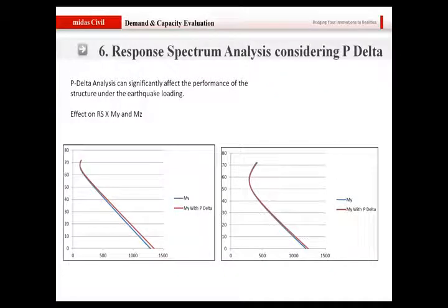Okay, so now let us talk about the spin-off of response spectrum analysis and pushover analysis and the recent developments. In this particular case, what I did was I checked the effect of P delta analysis if I take it into account in the demand calculation, and this is a comparison sheet that I have obtained, and here you can see that if I take into account the P delta analysis, the moment that I obtained will be on the higher side.